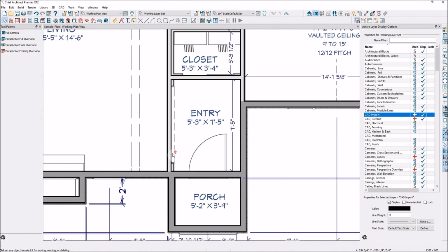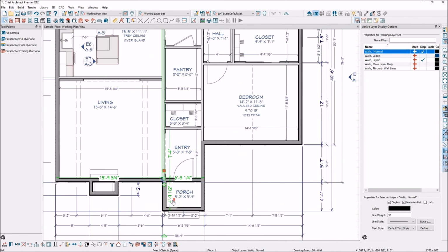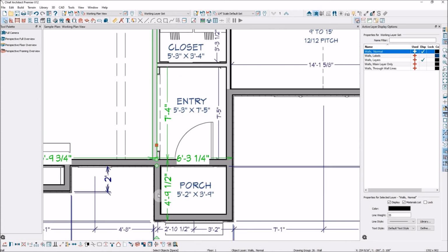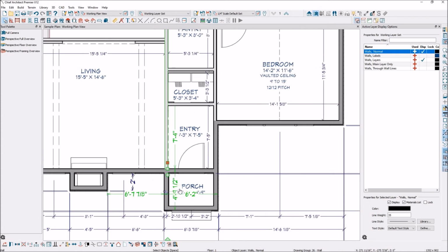And this wall that runs the length of the house, I want centered on this wall. So I'm going to use the center object tool. You highlight the object that you want, use the center tool, and center it on that wall. That's going to give me the perfect placement of where I want that wall to go.